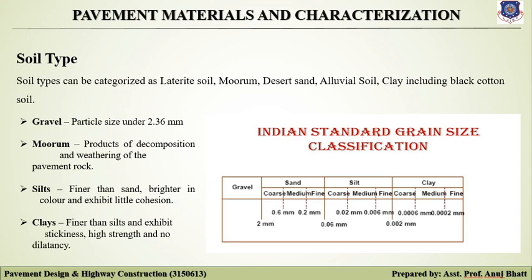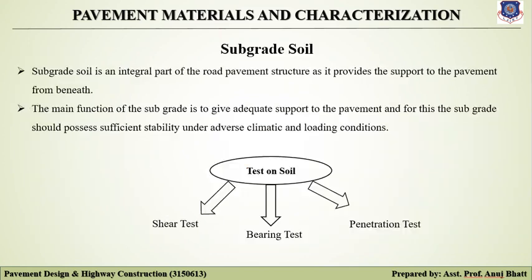To evaluate the strength properties of the soil, on site or in practice, we perform different tests on the soils. For the subgrade soil, we basically perform three different types of tests. First is the shear test, second is the bearing test, and third is the penetration test.